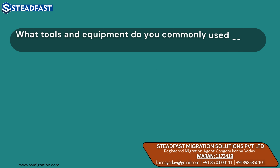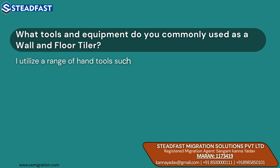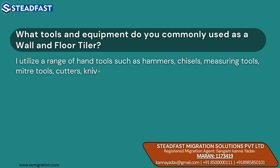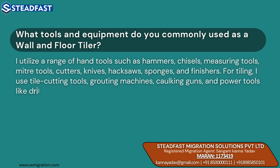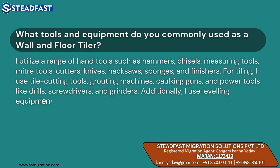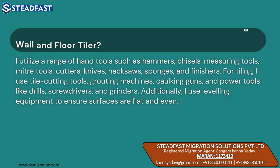What tools and equipment do you commonly use as a wall and floor tiler? I utilize a range of hand tools such as hammers, chisels, measuring tools, miter tools, cutters, knives, hacksaws, sponges, and finisher. For tiling, I use tile cutting tools, grouting machines, caulking guns, and power tools like drills, screwdrivers, and grinders. Additionally, I use leveling equipment to ensure surfaces are flat and even.